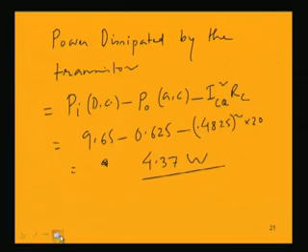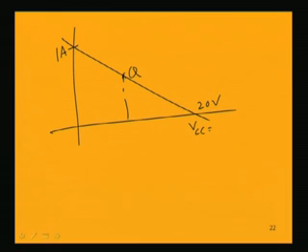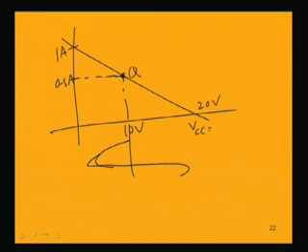What does it mean actually? That we are getting the Q point around the middle of the load line. In this particular example, we have now verified that the Q point is located at the middle of the load line. That means we are getting a symmetrical swing, these two halves are equal. This drawing should be proper. These two halves of this swing are equal basically.